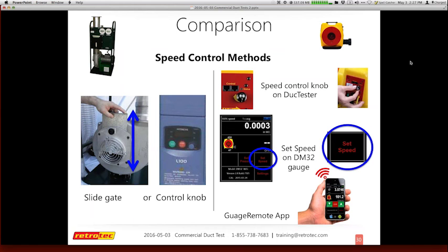I said it's totally impossible. So I discovered that if you take the duct blaster and you stall the flow, so there is no flow at all, which you see in the picture here, where the duct blaster is actually taped to the floor, so obviously the flow through the duct blaster is zero. You can see if you look at the gauge that it's actually measuring 706 CFM, and it's creating a pressure down there of around 414 pascals or so.